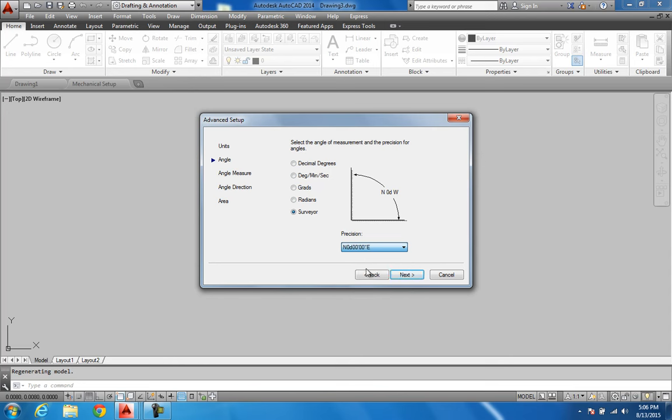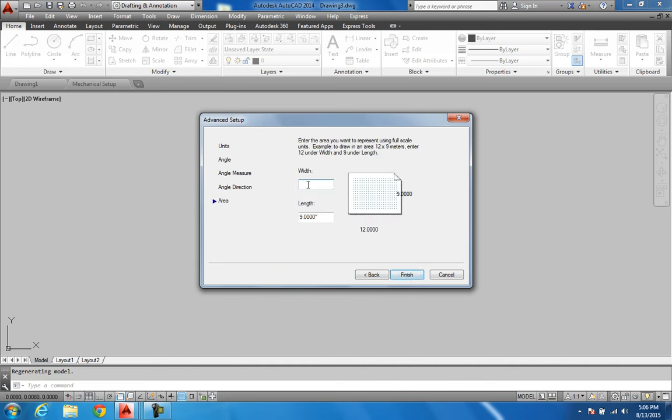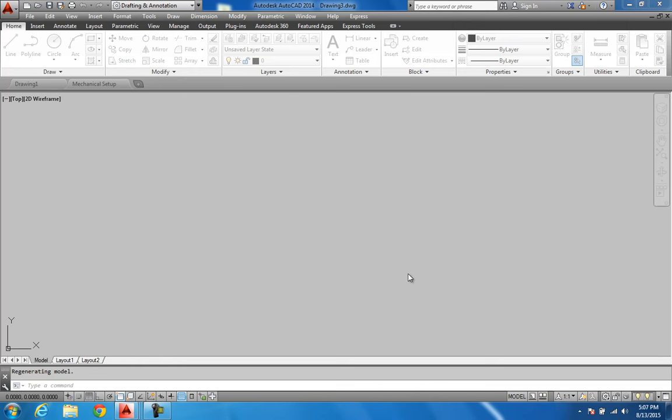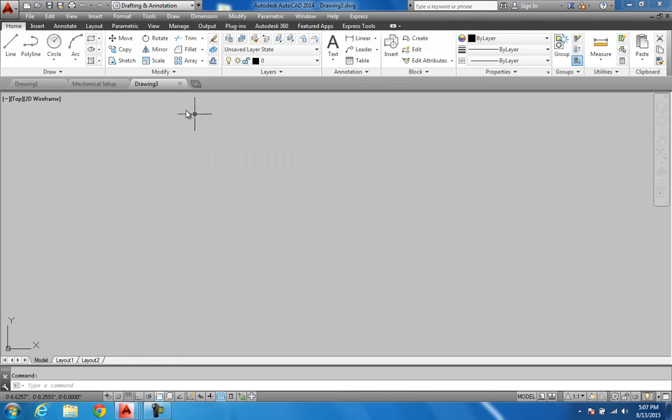Well, actually this one right here would be fine. Hit next. I'd leave all this alone. And now we can put in some big feet. Now I'm not for sure on your blackboard exactly what I ask you for, but you can type in 100 and put your little foot sign, and I'm just going to do 100 foot. Finish. And now just do a save.